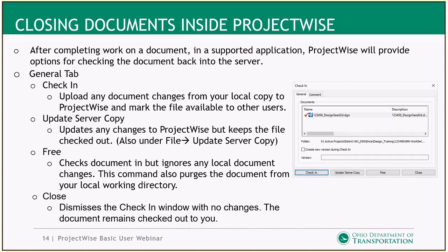Now the update server copy is a little different. If I hit update server copy, it checks all the changes back into ProjectWise, but it does not check the document back into ProjectWise. So you'll continue to see that red check mark, and others will continue to see that lock icon.